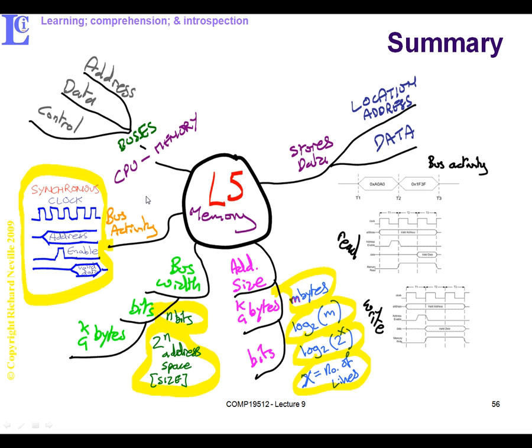And then if we look at bus activity, we saw that if we were writing or reading data nominally to primary memory, it took 3 clock cycles, and we had to remember there was a number of steps we had to take. First, the processor outputs the address on the address bus. Then the processor activates or enables a particular address line that tells the memory that that's a valid address, and that address line is the address enable line, and it goes high.